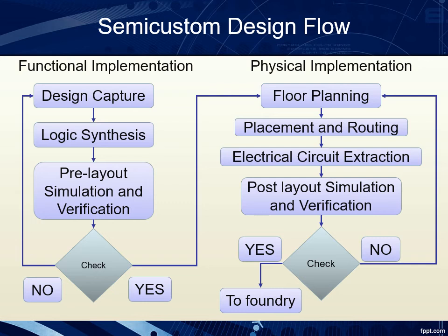First, we have the design capture stage, in which we basically use VHDL, the hardware description language, and the IP blocks that we want to use. After which we perform a logic synthesis using the necessary logic synthesis tools. At the end of which we have a list of all the gates, the so-called netlist, and then we have all the constraints in terms of placement and routing.